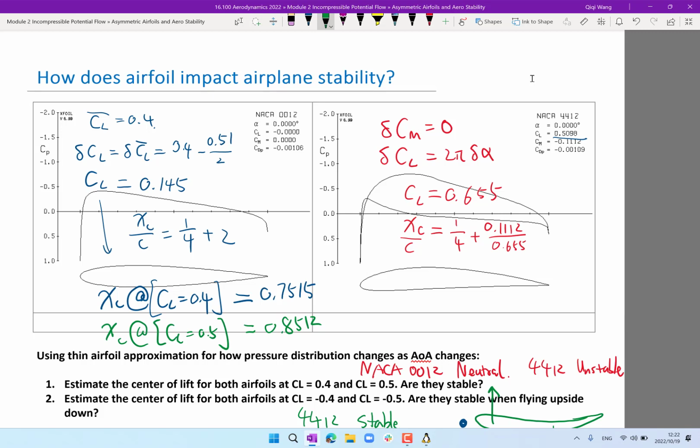This is because if you think about what the thin airfoil theory predicts, taking the entire chord length of 3 and multiplying by 1/4 is equivalent to saying that if you increase the angle of attack of the whole thing, the flow changes in a way that is similar to a flat plate between this and this. That is not the case.